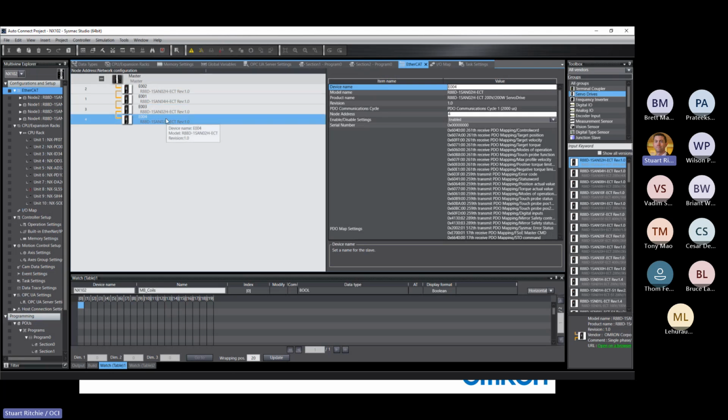It happens at a predetermined interval. With Ethernet IP, the data gets there when it gets there. If it has to jump through a couple of switches, it might have to wait in line, which is why you've got this fairly big window in Ethernet IP of when that data can arrive before you start raising alarms for not getting that data. So for precision control, for example in a motion application, EtherCAT is far better than Ethernet IP. But I will stay on the call after with you, and we can chat EtherCAT if you'd like. Yeah, thank you.